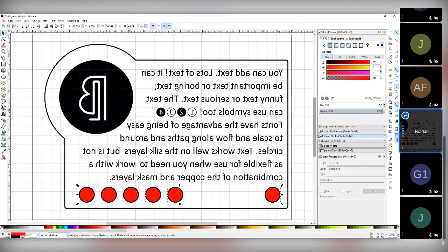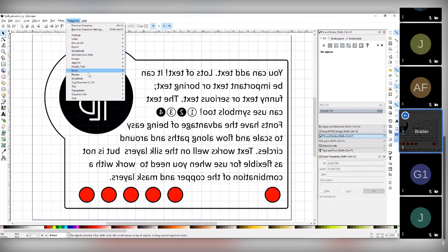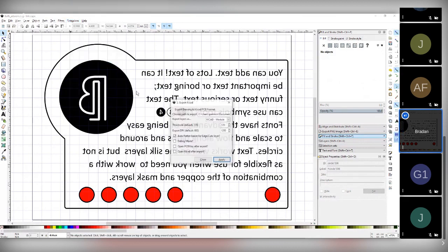Now you can get an idea of how this is going to work out. So we save this, and we go and regenerate our footprint. And actually, when it comes back, I'll show you what I was referring to on the transparency. Right here is the default threshold. So anything above 128 out of 256 will be part of the footprint. Anything below that will actually just be ignored.